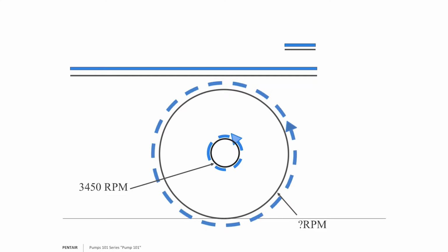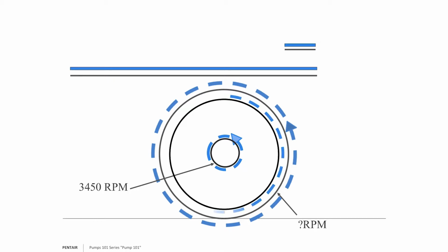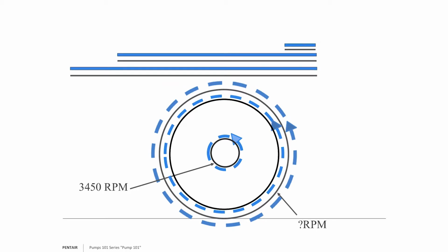When we cut the impeller down, meaning either intentionally trimming it or through cavitation, punching little holes in it, we've changed that radius. But we've also changed not the rotation, not the RPM, but we've changed the velocity because there's less radius. Less radius equals less velocity, which equals less pressure, okay? So that's what we talked about.